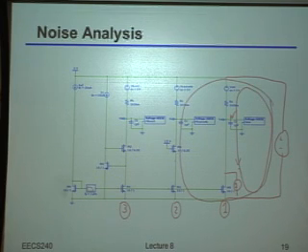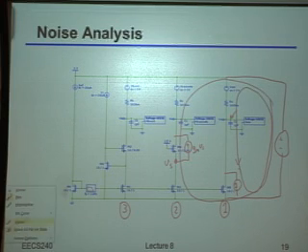Because if you think about it, the cascode, as long as it's been biased well and you have a reasonable gm ro and all that, largely speaking, you would just see the gm of that cascode device looking up, right? And so indeed, all of your current would basically just flow through that loop. Okay? Now, however, let's think about the cascode itself.